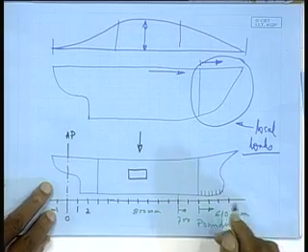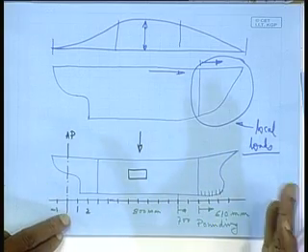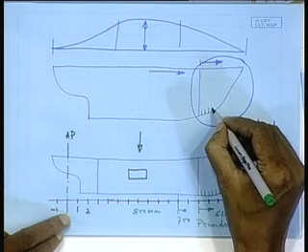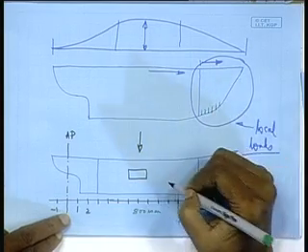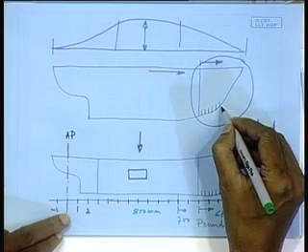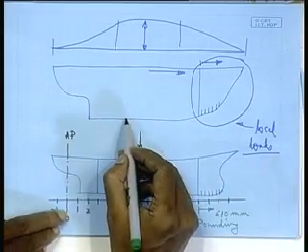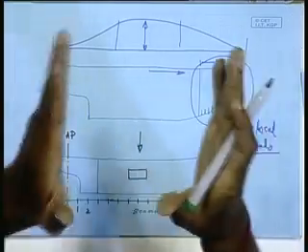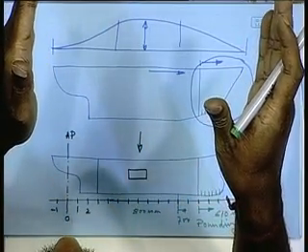What are those transverse members? They are the floors, you know, those plate floors. So, you will have plate floor at all places, at all frame spacing to a certain extent. Right. Here we had plate floors at every 3 to 4 frame spaces. In between we had bracket floors.